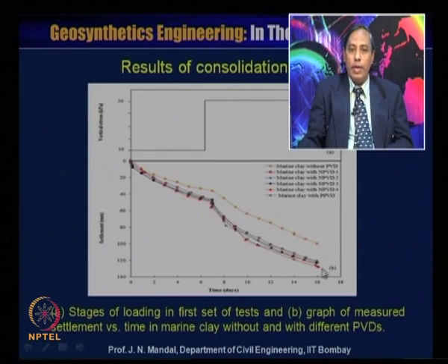And then after some time it will also stabilize, but you may require a very large scale consolidation test which can give you the equilibrium state of the soil, or it will stabilize at a longer time, which here seems to be a limitation of this equipment. So, you will be able to say that up to this many days the settlement may occur, that is the maximum you can obtain from this curve.